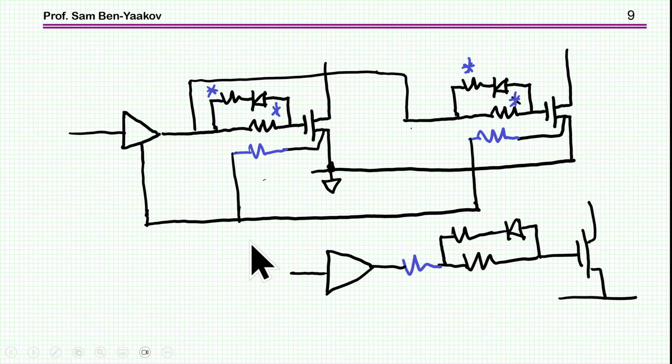Now, a possible remedy for this is to add these resistors. Well, the idea is that by this resistor, you reduce the circulating current, and the voltage drop here on this line, which usually is going to be a fairly small, thin wire, so it's going to be very heavy copper. The voltage drop on it will be much lower, so therefore the gate to source voltages will have less noise on them.